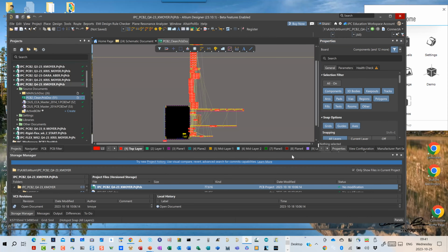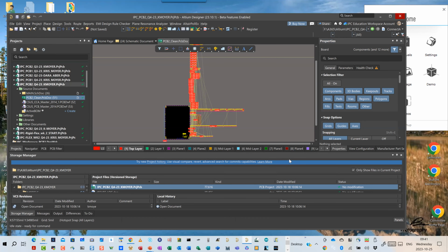What could be a good practice to clean the flux? So there's two primary practices. We're going to talk about those next week. There's aqueous wash and solvent-based wash. You can do ultrasonic or traditional. One of the most classic ways to wash it is basically an industrial dishwasher. It literally has a pull-out rack, just like your dishwasher at home. You'll stack the boards in it like they're the dinner plates, and it goes through and uses deionized water with a saponifier, basically a soap, that dissolves the material off, rinses it off, and you go from there. That's assuming that all the parts on your board are capable of going through an aqueous wash.